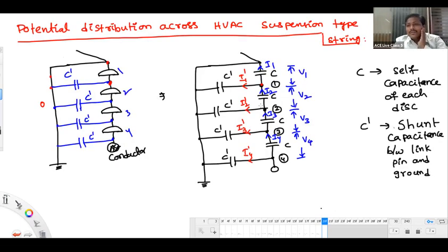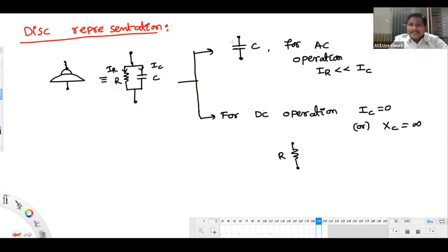What is that current I2 we can write? Simple. Look here. This is one capacitor. We are applying some voltage across the capacitor as V, let us say. And how much is the current I we can say? V by XC is the current drawn by that capacitor. I equals V by XC. Yes or no? And what you can write for that V by XC? That is simply V into omega C. So current in a particular capacitor equals the voltage across the capacitor multiplied by omega into the capacitance value.